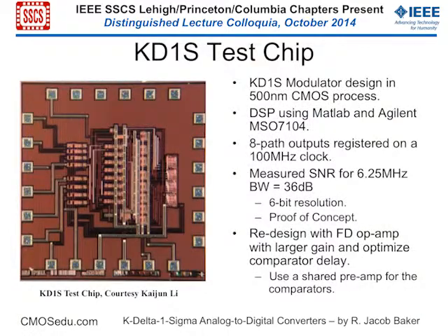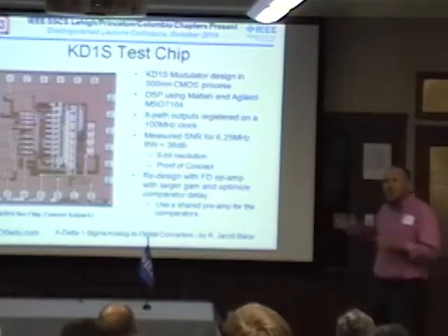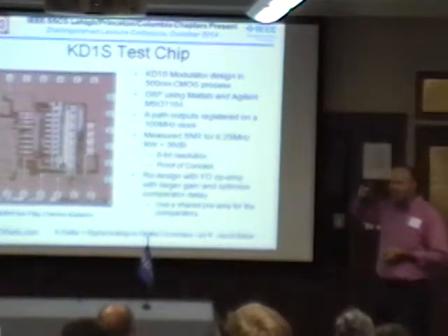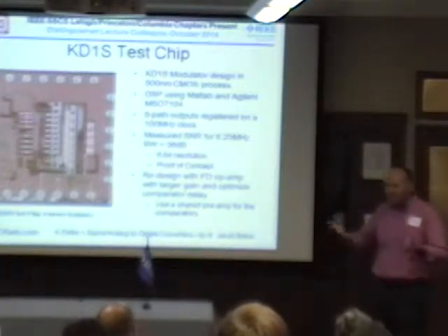Before I forget, and I'll probably mention this again, this topology, say you're going for 6 bits, is great for very high speed. One thing I've been looking at lately is SerDes, serializers and deserializers, and they go to very high speeds. People are predicting that the bang-bang PLLs they currently use are going to run out of steam.